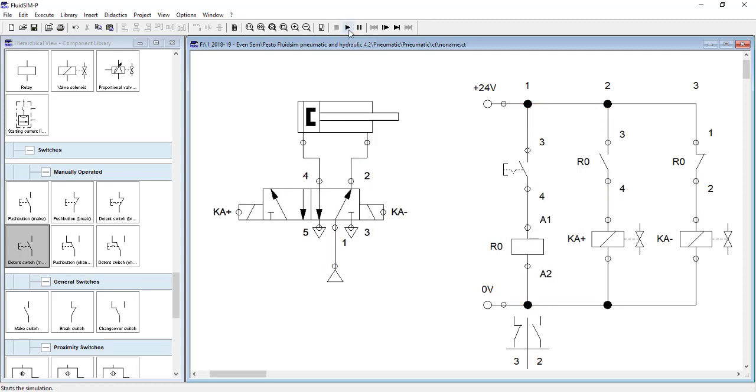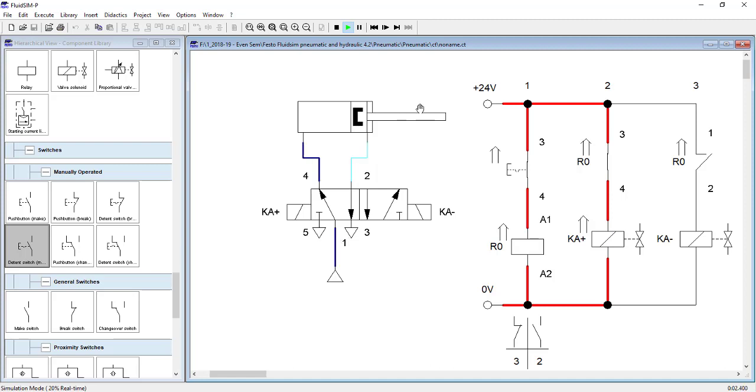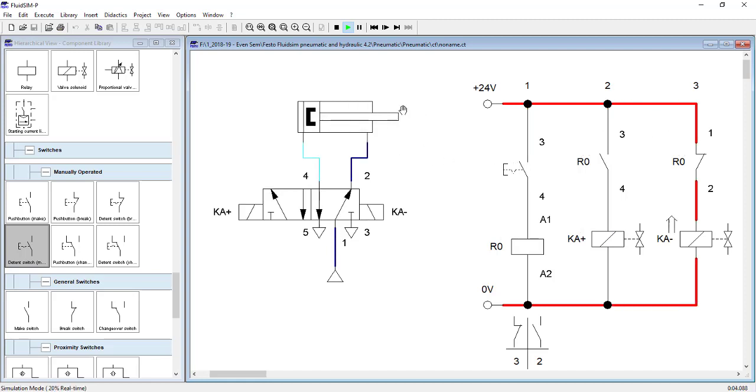So see, how will I know when the piston has reached its complete end positions? To know whether the piston is in its initial, completely retracted position: now the piston is completely retracted, so I know it must move forward. Once it moves forward, I should know that it has reached its extreme end position, and now it should move backward. So I should know the current position of the piston. Only by knowing the current position can I control its motion.